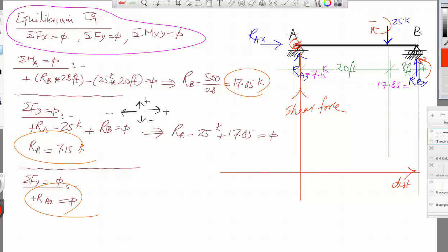So what we're trying to do here is we'd like to calculate the shear force at a distance, for example 7, then shear force at a distance of 15, shear force at distance 20, shear force at distance 24, and then until we get to 28. And then we have these points, 1 point, 2 point, 3, 4, and then we draw the diagram. This is the idea. So the idea again is to find the values for shear force. These are shear force, right? And these are the distances. So after that we sketch the diagram. That is the task that we intend to do.